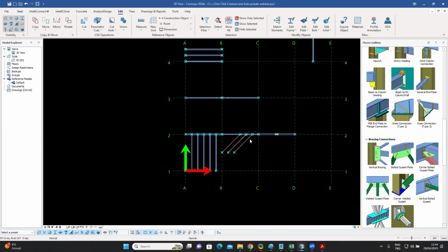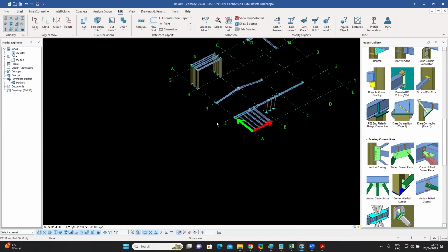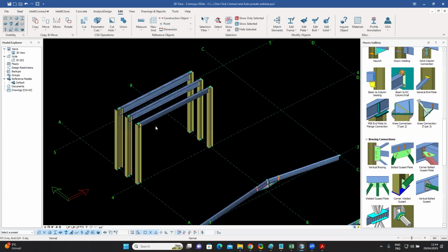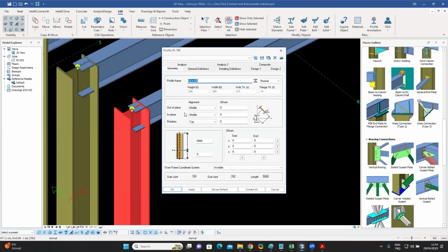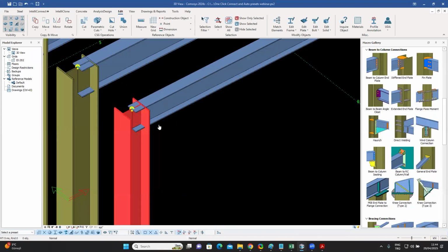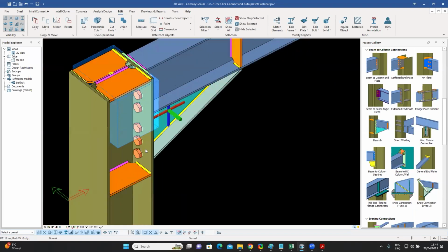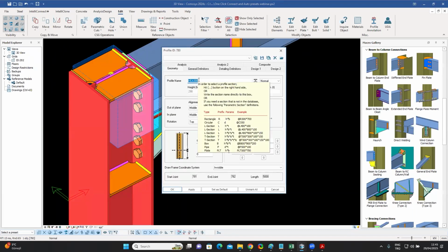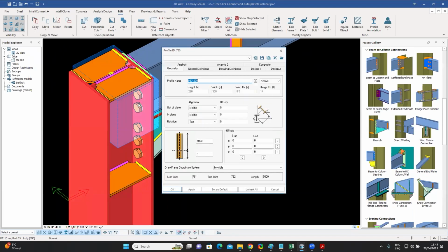Now, another example I can do is of flange bolting. So let's come over here. This is an I-beam, HEA 300. Let's say I make a haunch connection over here. Now, one thing which always takes time is whenever you place bolts on the flange of an I-section or on the flange of a channel, the exact location of the bolt is specified by the standards. So it'll say, for example, that for HEA 300, the bolts need to be placed exactly at a certain point.